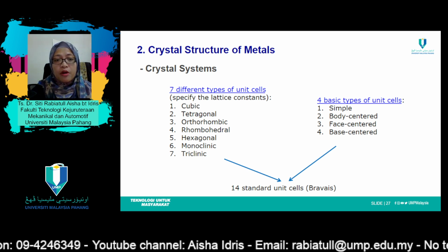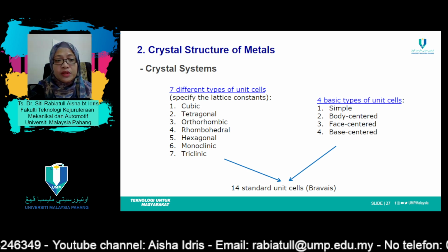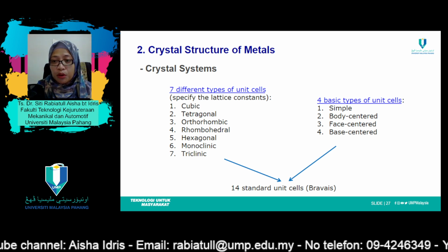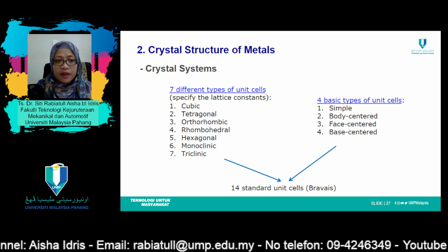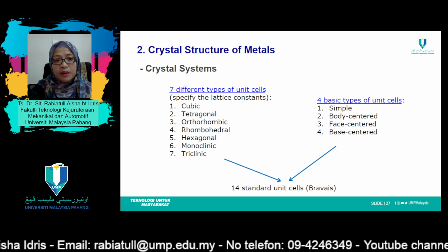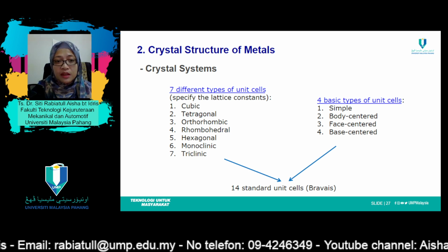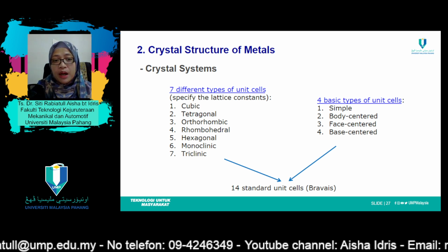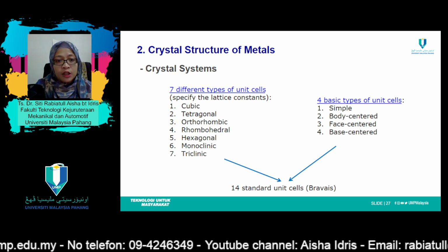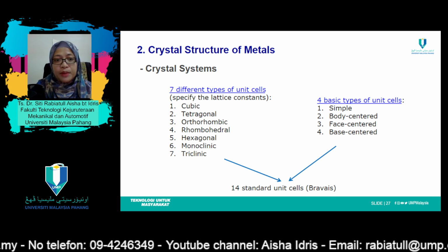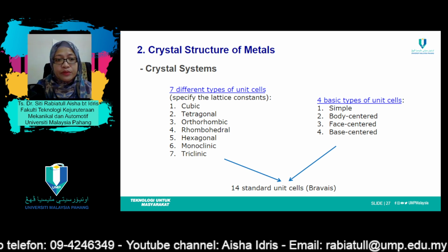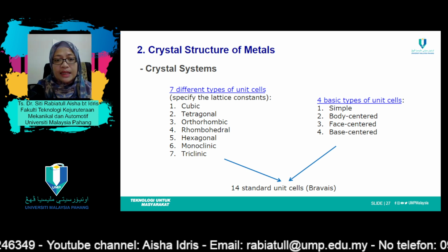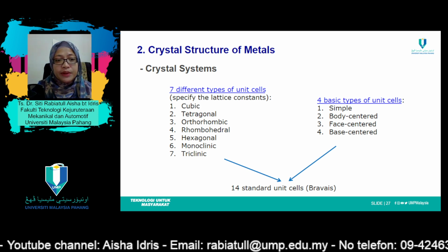The smallest group of symmetrically aligned atoms which can be repeated in an array to make up the entire crystal is called a unit cell. There are several ways to describe a lattice actually. The most common description is known as the Bravais lattice. In words, a Bravais lattice is an array of discrete points with an arrangement and orientation that look exactly the same from any of the discrete points.